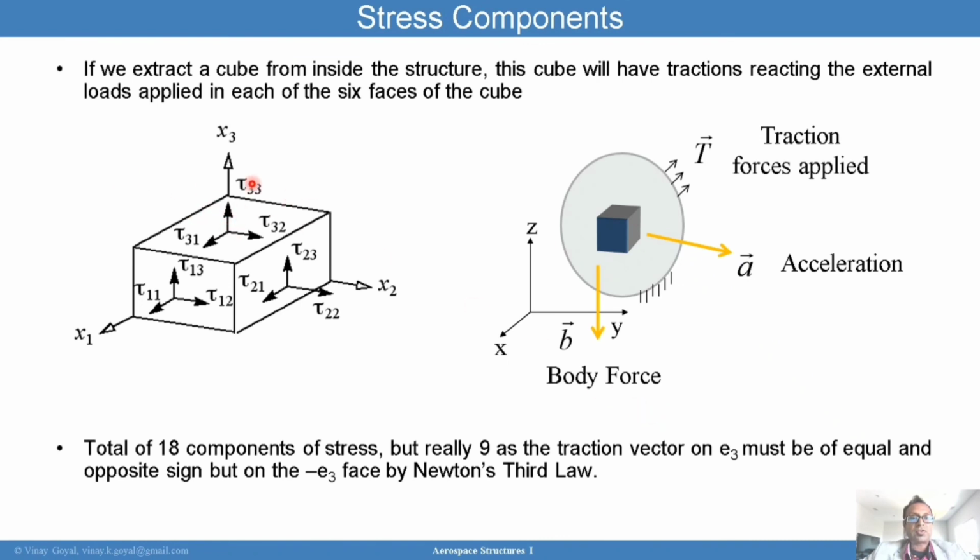And that traction vector can be decomposed into these 3 components. When I look at phase 1, you're going to see here 2 indices. Let me go through that. The first index is 1, and it represents the phase on which those tractions are being discussed. So these stress quantities here, tau 1.1, tau 1.3, and tau 1.2, and we're going to use sigma as well in this class. Tau and sigma are stress quantities, and we're going to interchangeably use them.